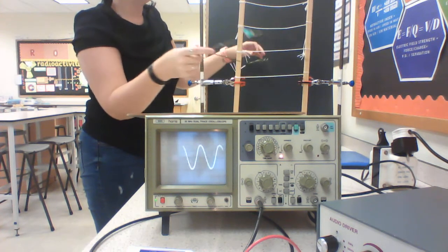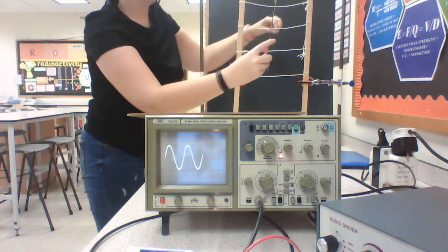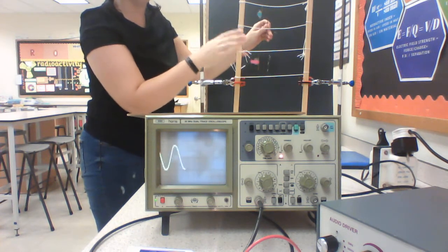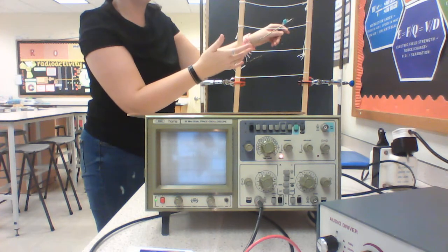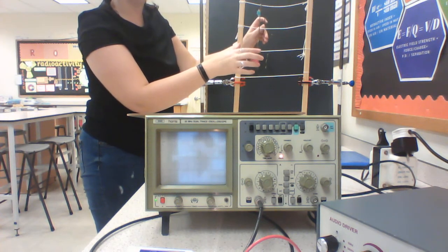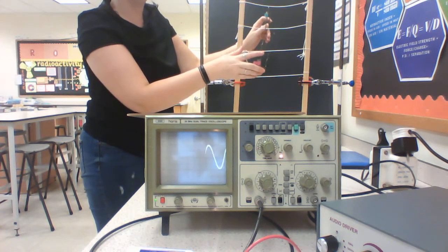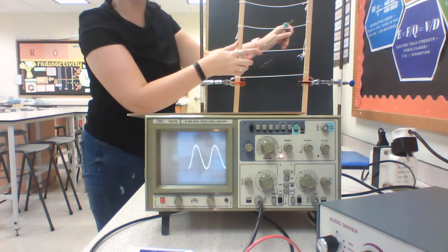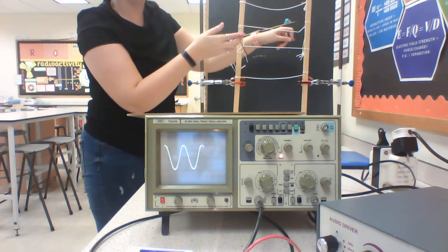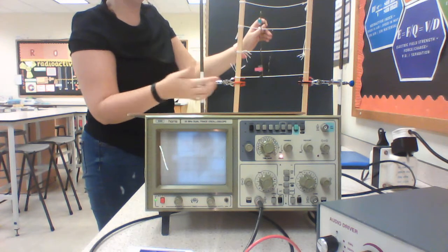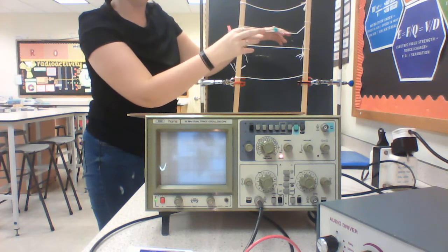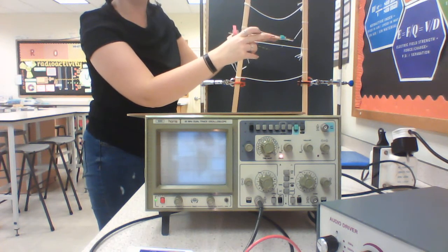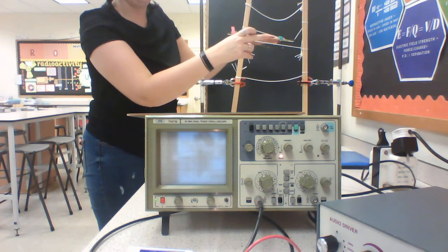pretty large. When I'm at 0, that's when you have the maximum flux inside my coil, but as it turns, it doesn't cut any more flux. I haven't got a big change in flux. I've got lots of flux inside my coil, but my change in flux actually doesn't really get anywhere until I get horizontal again. So that, when it's perpendicular to the magnetic field lines, is actually when you have 0 induced EMF. When it's horizontal or parallel to the field lines, that's when you have your maximum EMF.